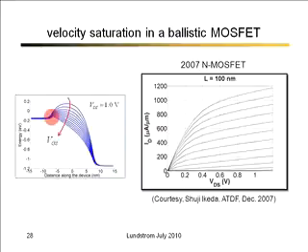And this is something that confused a lot of people, myself included, for a while. If you look at the IV characteristics for this MOSFET, one of the signatures of a velocity-saturated MOSFET is that the current under high VDS increases linearly as you increase the gate voltage.